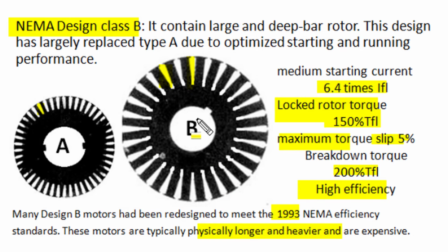They have a larger diameter and length so as to reduce specific electric and magnetic loading for the same amount of power output. And these energy efficient motors require a higher amount of active material, winding conductor material and core iron material. So they are a bit expensive, but in comparison to a standard class B motor which has an efficiency of the order of 85 to 88%, these high energy efficient motors have an efficiency of the order of 90%. New energy efficient motors have 2% extra energy margin.